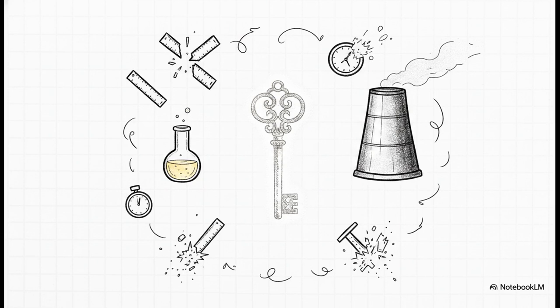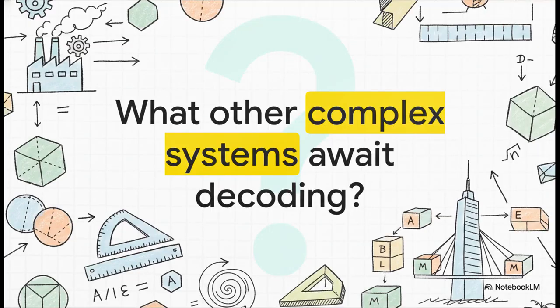By carefully combining those physical parameters, engineers convert complex variables into dimensionless numbers. Because these numbers have zero physical units attached to them, the units have all canceled each other out, they act as a universal translation key. A dimensionless number behaves exactly the same way in a tiny 1-liter beaker as it does in a massive 10,000-liter industrial reactor. It's brilliant. By understanding the fundamental language of dimensions and forcing our math to obey the rules of homogeneity, we completely unlock the ability to scale up modern industry.